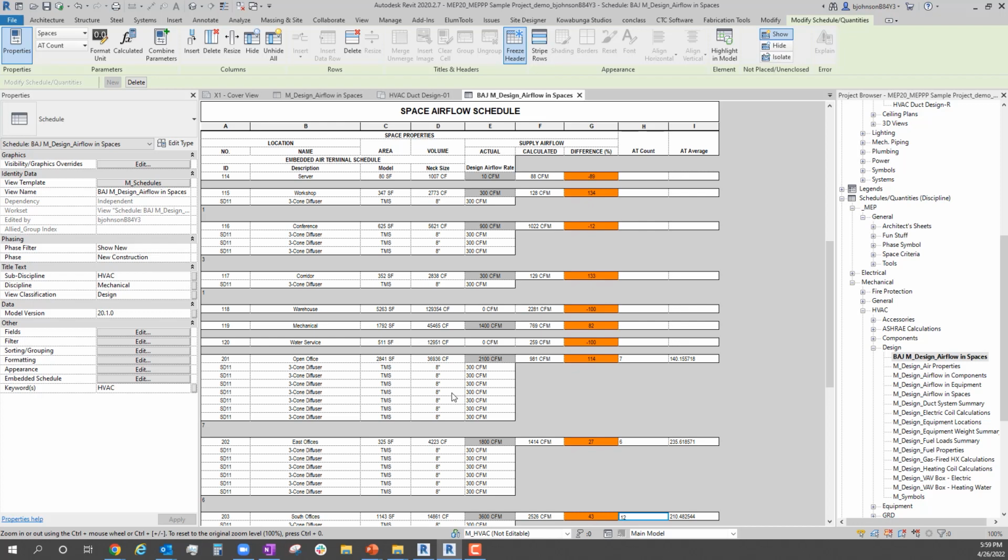know that if I change size, chances are there won't be enough room for the fitting and I'll get a disconnect. And then not only do I have to fix the air terminal, but I also have to reconnect it after the fact because it disconnected because it deleted the fitting. So how much more work am I adding to myself by changing, upsizing, or downsizing elements that are in my connected workflows to get it to work exactly the way it should?